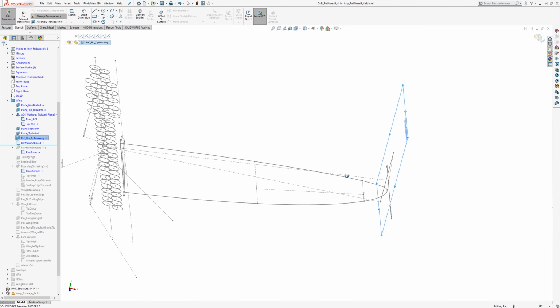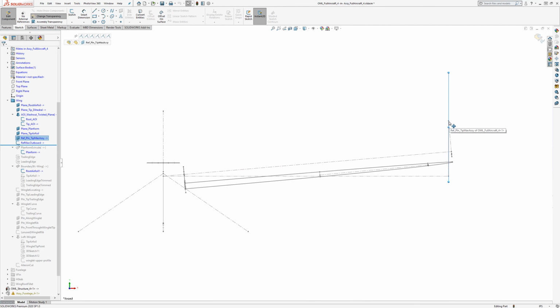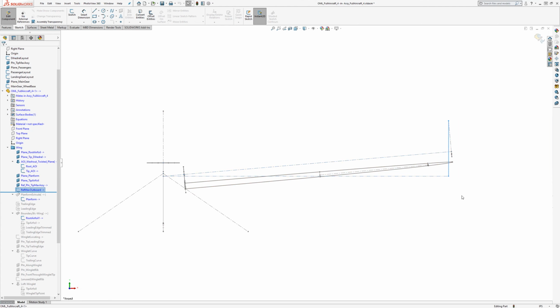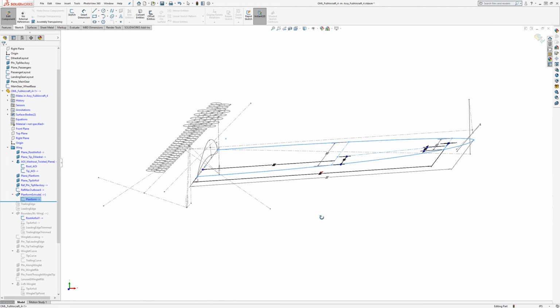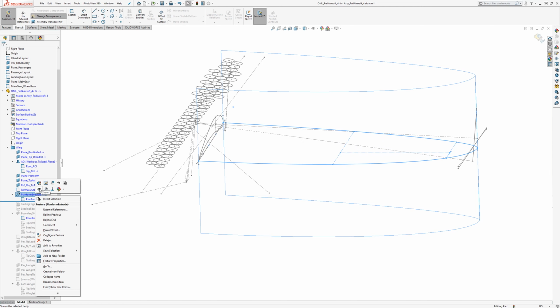So we also have this plane to reference that no part of the wing can exceed this plane, even though some of the planform sticks out beyond this plane here, because that's beyond 72 inches of this portion. So at the end with our winglet, this will curve up and not go beyond that point. Then the planform within the plane of the planform gets extruded as a surface.